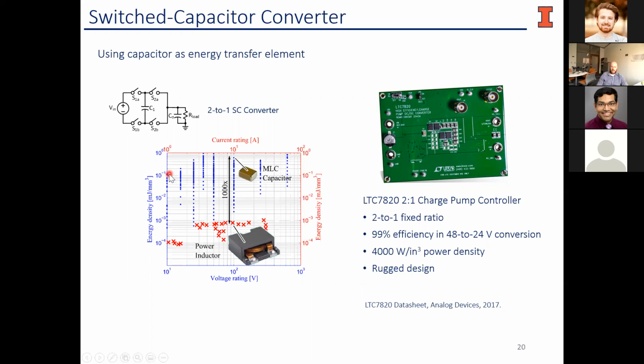As we scale down in this space, fundamentally, it comes down to a case where these capacitors are kind of 2D devices. We're really just looking at the dielectric, how good the dielectric is, how close we can get those plates and still stand off that voltage, and then how we can cram them into a nice small package. The inductor ends up being a little bit more of a 3D device.